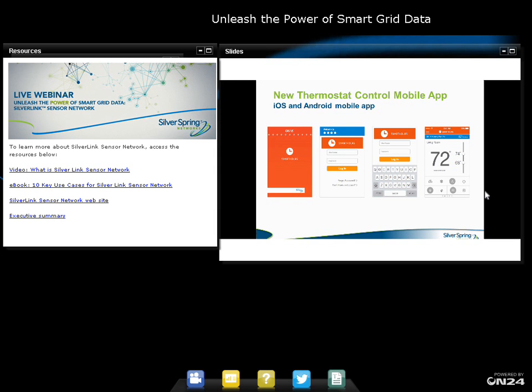And compress it in a couple interesting ways. You can use standard compression algorithms, but you can also just put some rules on the NIC that tell you when the data that you're interested in occurs. So for example, instead of sending every voltage interval back, you can send just the sags and swells back and an occasional summary set of information to tell you how the voltage is doing.